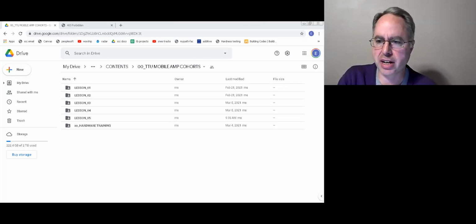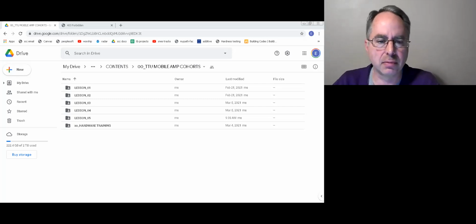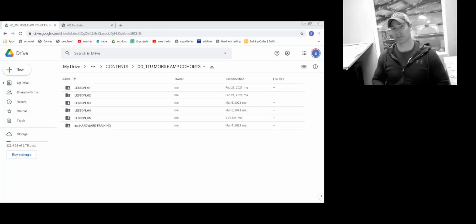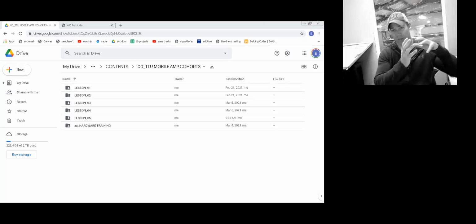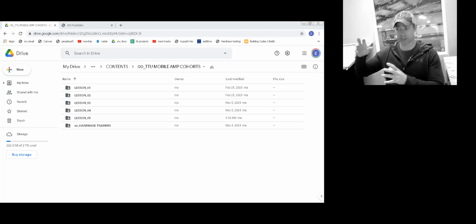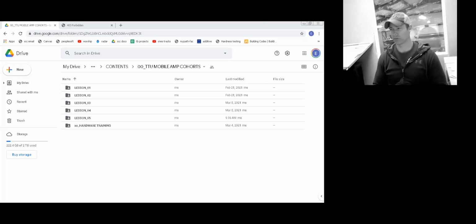So that's generative design. Okay, yeah. But it's actually two things: generative design and lattice structure within topology. You've got one group doing generative, another group doing this lattice structure stuff, and they are independent of each other, but they can be merged. They're both using artificial intelligence to re-optimize. One does it by thinning everything out and making it look very organic. The other does it by cutting chunks out and making it a diamond structure or Voronoi structure, all kinds of cellular structural shapes.